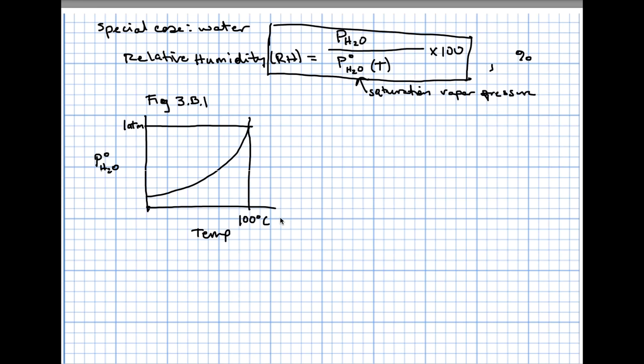At sea level, where the pressure is 1 atmosphere, if the temperature of the water reaches 100 degrees C, it boils, and that's because its vapor pressure has been exceeded. And then, as you know, if you're at a lower pressure, so as you go up in elevation, then water boils at a lower temperature. Okay, so I'm illustrating this relationship here.